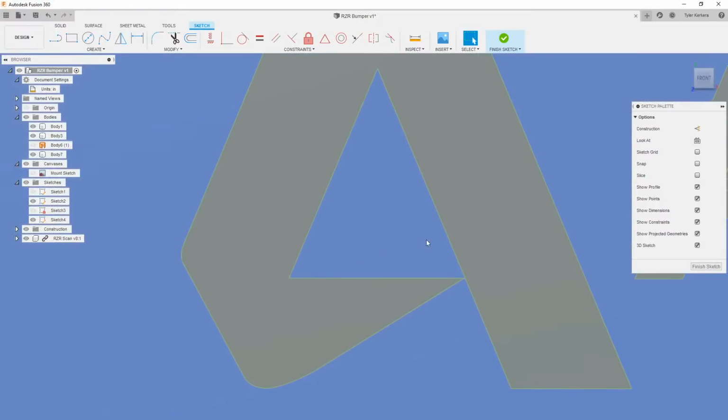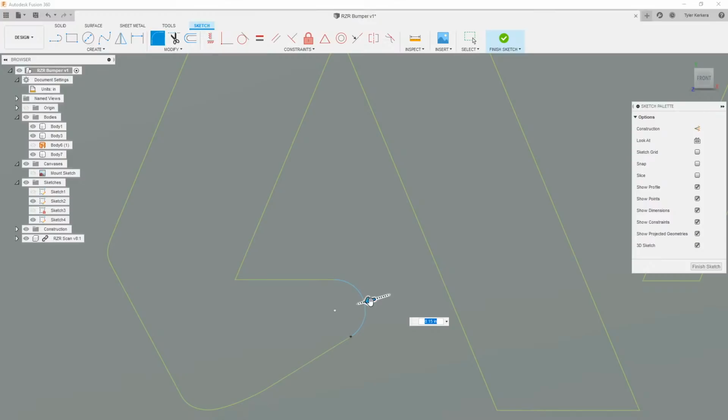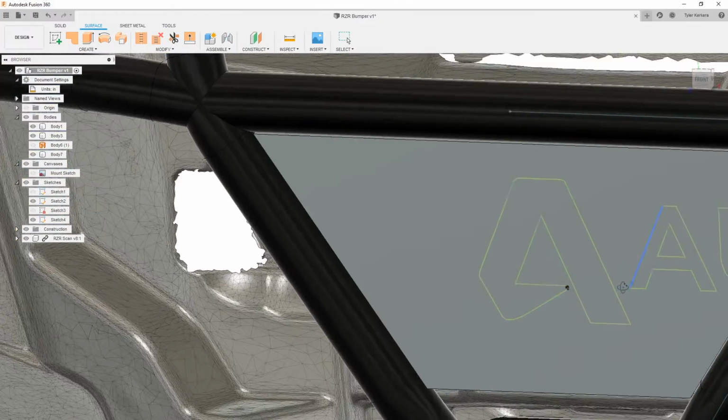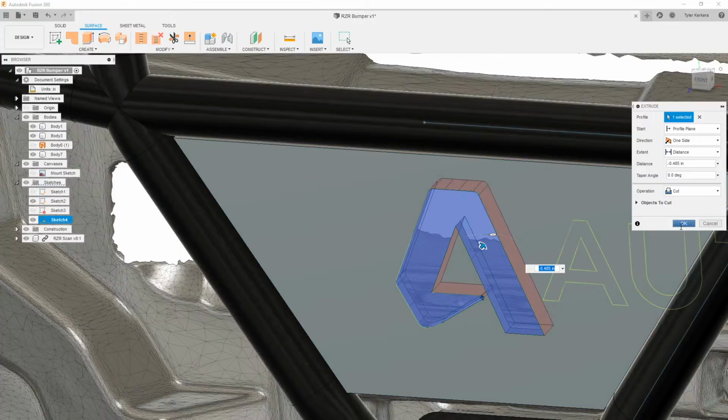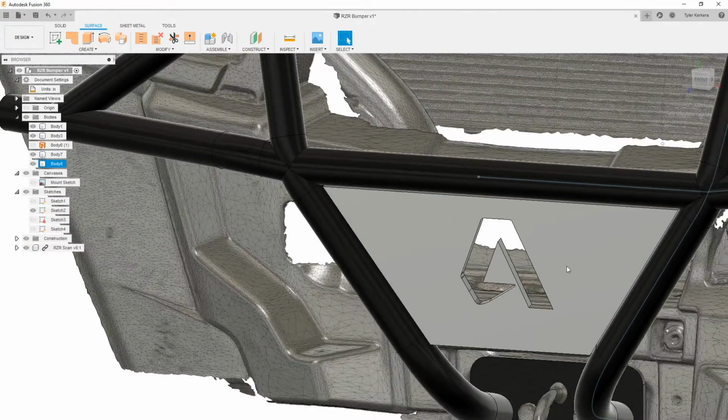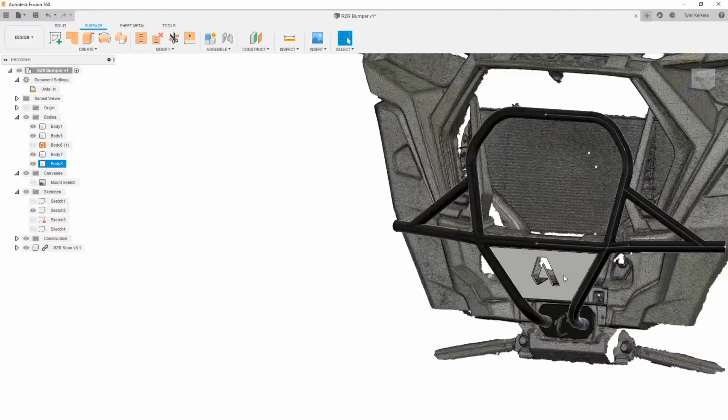And well, I imagine this would be floating or be hanging on by a very small piece of metal if this existed the way it does now. So maybe we'll round this out, give that a little bit of room to attach to. Say finish. Go through and cut this through the part. And that looks pretty good.